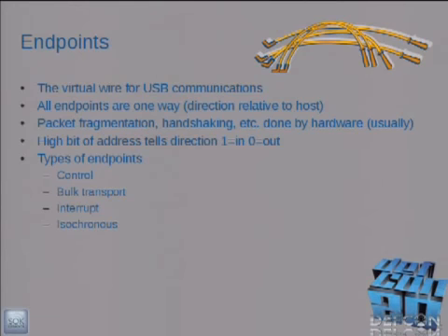And the address for each endpoint has a meaning. The high bit tells you whether it's in or out. And there are various types of endpoints. Control endpoints are something that every device has to have. You can have bulk endpoints, which we'll talk about a bit today. Interrupt endpoints, and also isochronous endpoints.